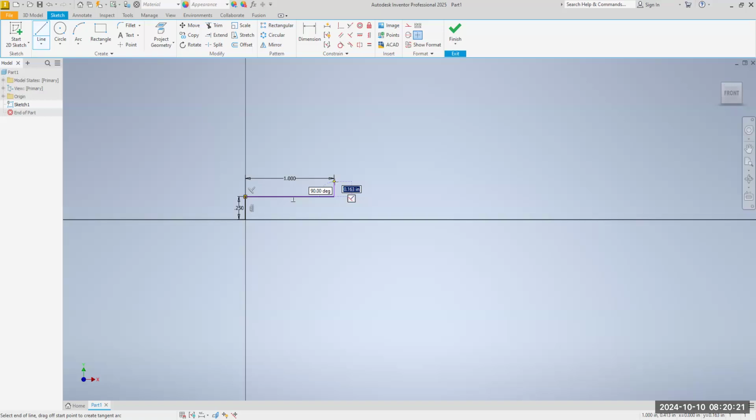It's under A. They gave you the max and the min. Give me the max. It's 0.750. You see that? Okay. So I've already gone up 1/4 of an inch. I've got to do half. So if I've gone up 1/4 of an inch, I've got to go up another 1/8 of an inch to get half of the diameter of the head of the screw. So we're going to add 1/8 of an inch here.